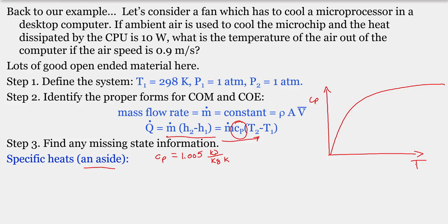There are 2 ways you can make that approximation, and it's a good approximation. One is you say, hey, look, my problem considers a temperature region where the specific heat really is approximately constant. So you can say, I'm at a sufficiently high temperature where this is a good approximation. Alternatively, you can be in these regions here where you do see some variability to the specific heat, and you have 2 choices.